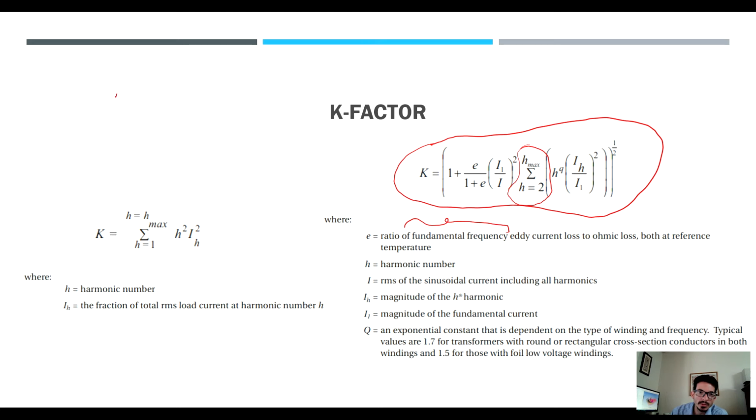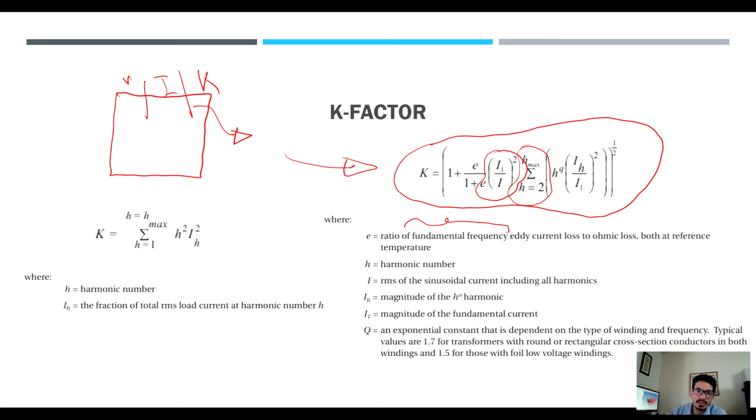But when you go to buy a transformer, they're gonna give you a chart with voltage, current, K factor. Okay, so obviously you want this K factor to be, again, this is something that is based on people who build transformers, but the point is that if you use a transformer for an application where the current is bigger than what it's supposed to be rated at, then if your transformer still works, it's going to be less efficient. And the reason is because it's not in the envelope of the K factor that it was designed for.